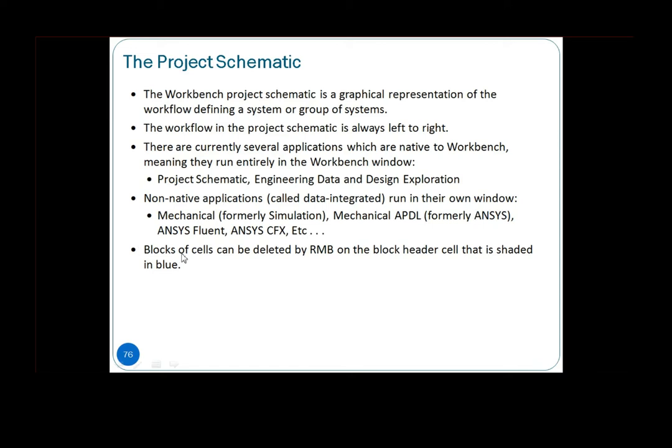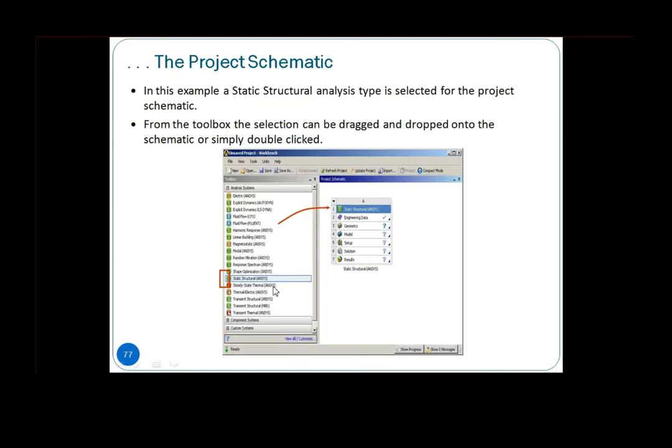Mechanical, APDL, ANSYS CFX, Fluent are all separate windows or applications. Okay, so if you want to delete, you right click of your mouse, okay, right mouse click, then on the block header, then you can delete it. So this is the project schematic section.